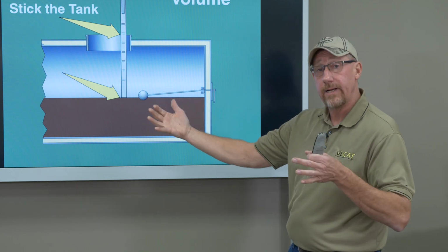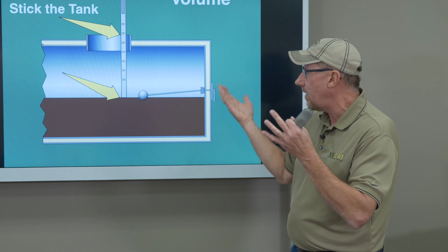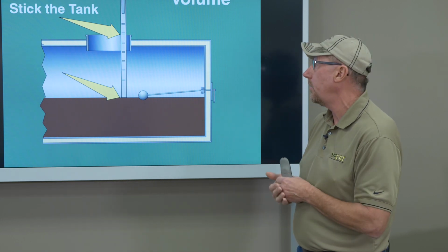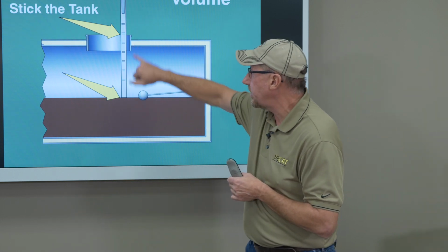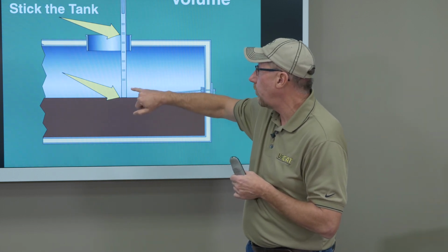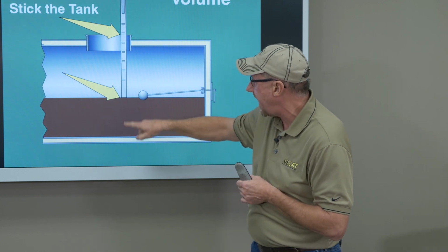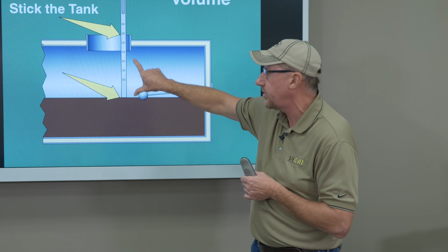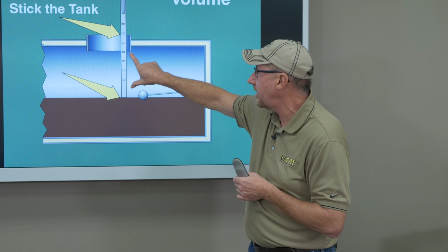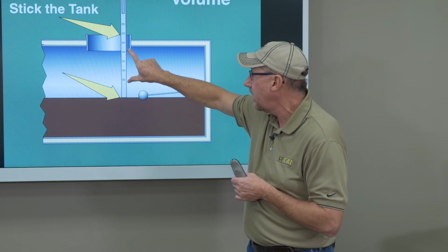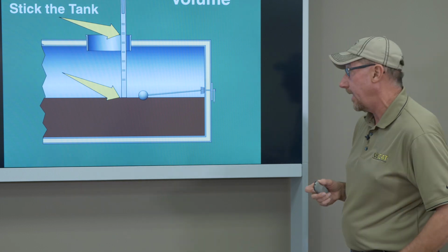Spray a certain distance at a certain width. Use the stick again. It will tell me, do the math and figure out how much you used compared to the computer. That will tell you if you're within calibration. Now on competitor machines, their sticks are not reverse calibrated, so take their stick, put it all the way in until it hits the bottom of the tank, and then wherever the oil line is in the stick, use it that way, because there's two different styles to that. But you want to make sure that every distributor ever made has a calibrated stick for that distributor. So that's the easiest way to check it on the job.